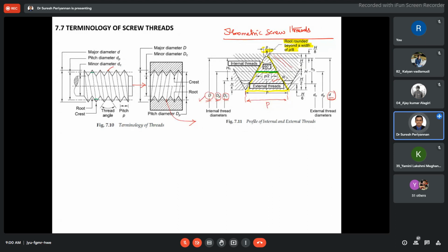Now see here, I told you about the coarse series first. Now the fine series, fine threads. What is the advantage of fine threads? Fine threads also have some advantages. Fine threads have greater strength, because the number of threads will be more. Hence, it creates more contact region between the nut and bolt, so there is more strength. Fine threads we always use for fluctuating loads, and fine threads are suitable wherever vibration is possible. Fine thread is much appreciated there, as it can be better to avoid vibration; vibration can be easily absorbed by the bolt and nut. So fine threaded bolts and nuts are better in vibration regions.